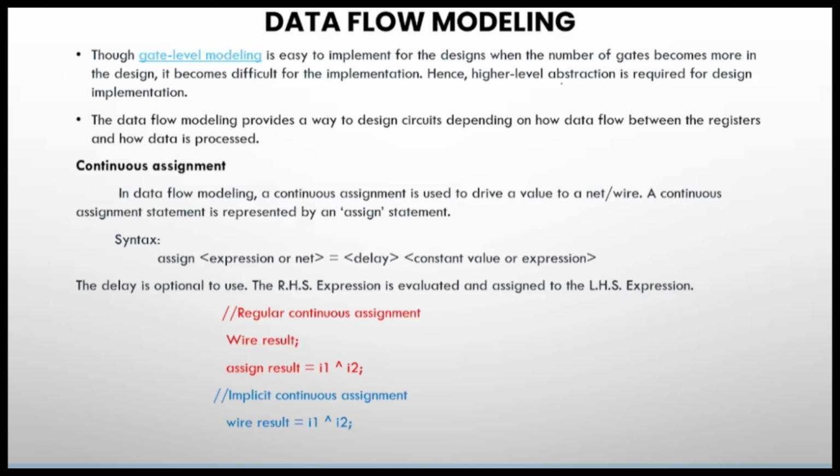Clear? Yes. Now coming to data flow modeling. In gate level modeling, you write the code based on the gates, based on the structure. But in data flow modeling, you write the code based on how the data is flowing. That is why this is called data flow modeling. It is about how the data is flowing between your registers, and based on that, you create the data flow model.